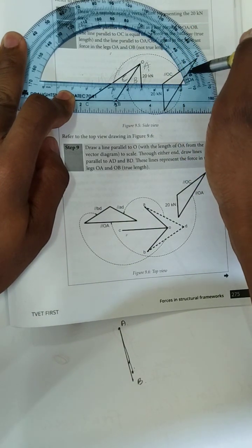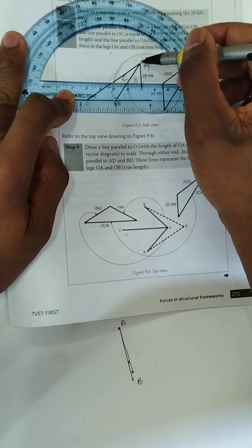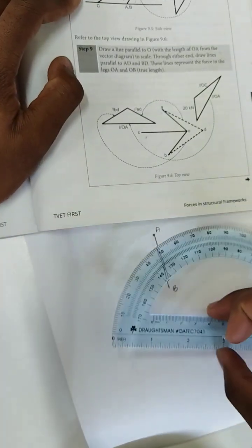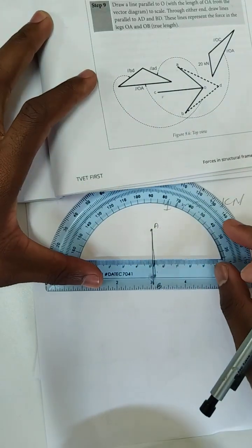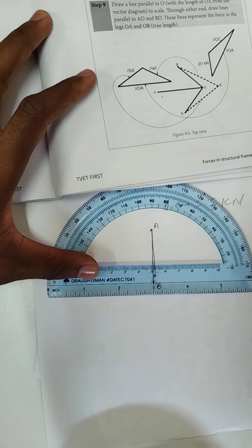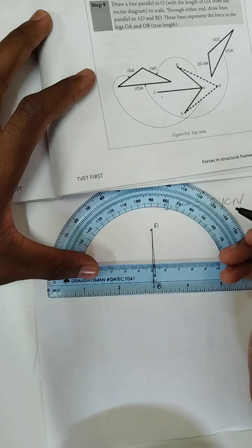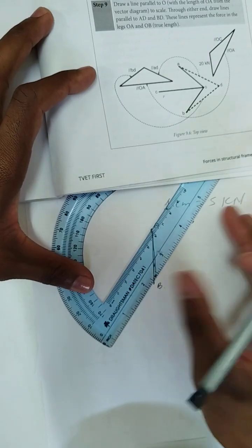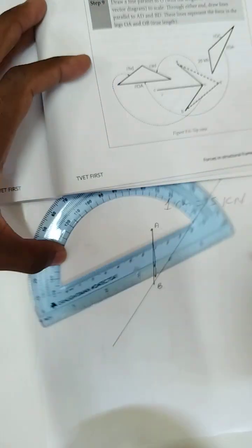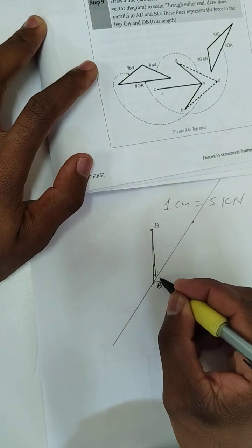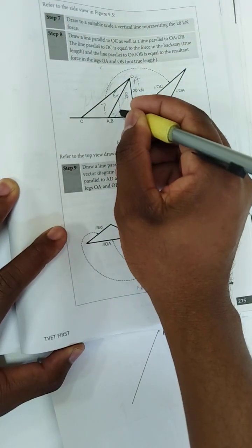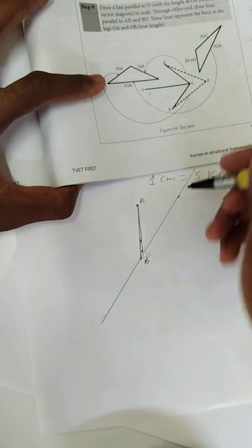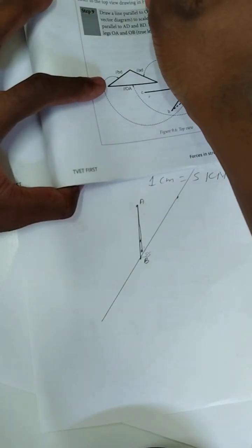It's 10, 20. It's giving me about 55. Okay, 55. Then you come to B here. Here is B. And then you mark an angle of 55 somewhere here. Then after that, you extend this line like this. So this angle must be 55, which is the same angle as this one, which is 55. So this line is parallel to this line.